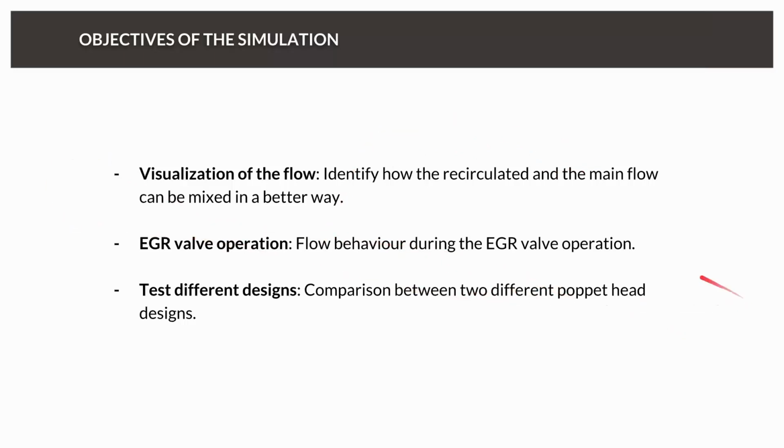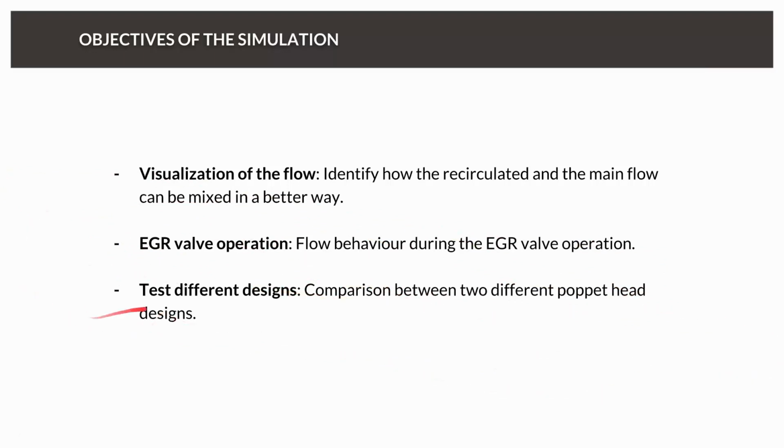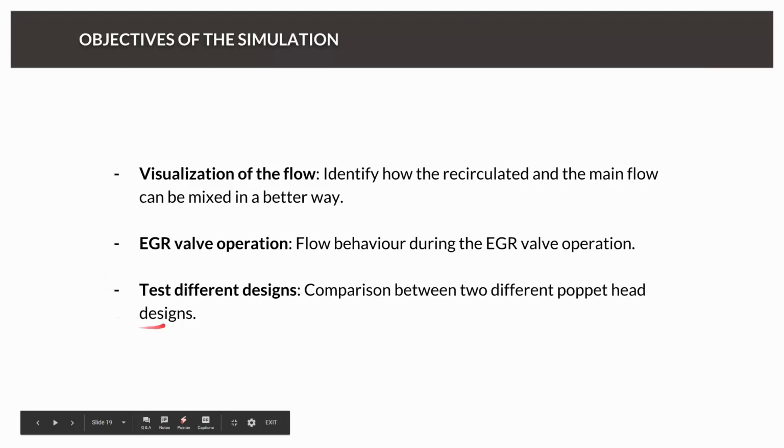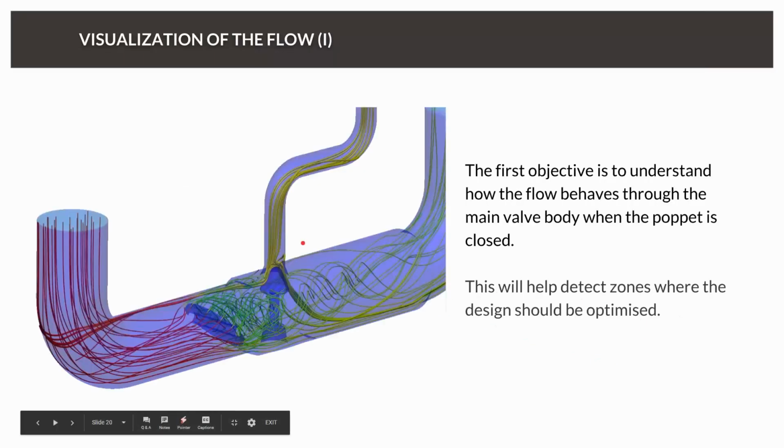Another thing which is very interesting: when you visualize the flow conditions, we really want to take a look at the static points, but usually during the valve operation, when we switch from one valve state to the other, we will have some transient phenomena, which we can also investigate with the help of simulation. And finally, we can also try to optimize the design, and we'll test different poppet head designs.